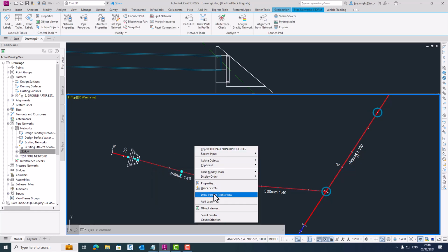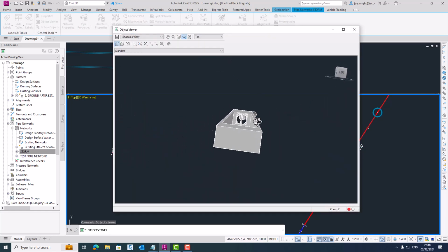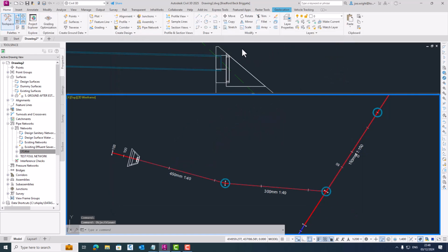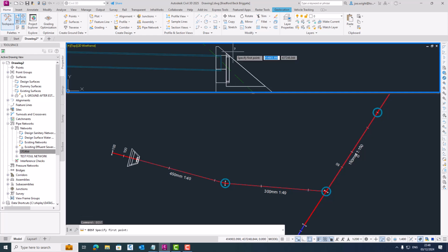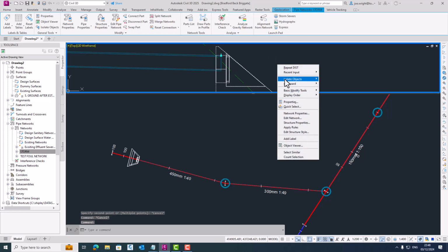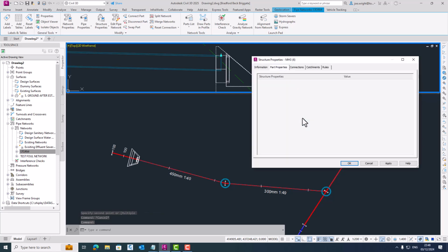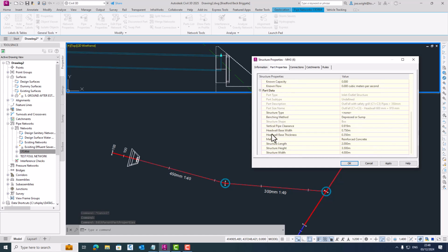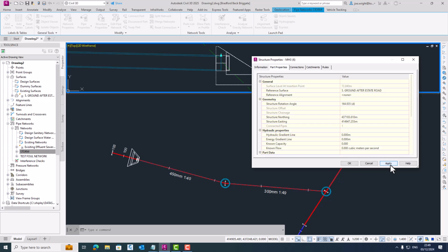Let's check it out in 3D. Ooh, that's no good. It can be changed, and the variable needs to match the outside diameter of the connecting pipe. So let's measure it. 518mm. Now, in designing the model, and to get this working accurately, I had to hijack a variable, namely vertical pipe clearance. Here it is. It just needs to match the 518mm measurement.